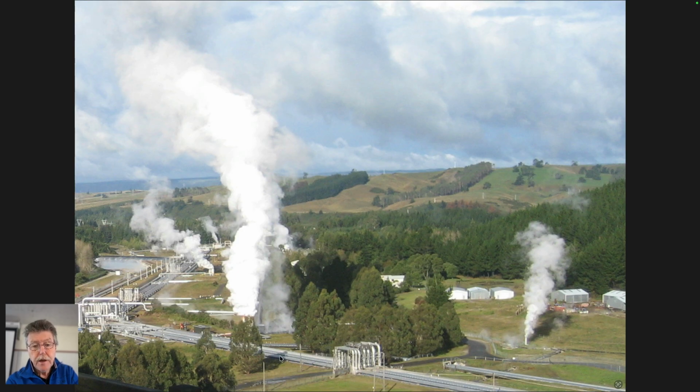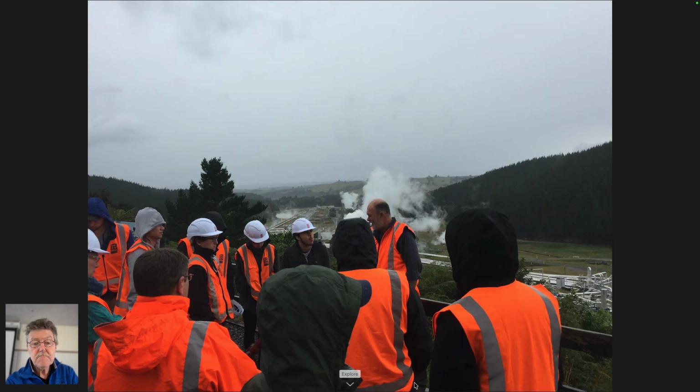These are the pipes supplying hot water to a centralized geothermal plant somewhere down here, going across roads, lifting it above the roads, but also allowing expansion. These pipes would be seated on rollers, so as they expand and contract, they're not physically anchored, but they just sit on a roller which is able to allow them to move laterally.